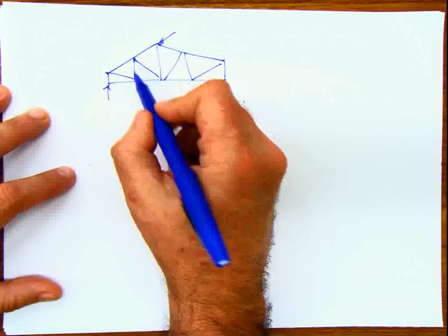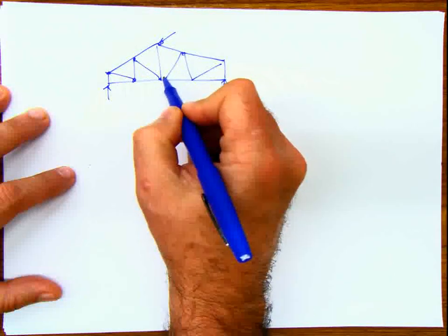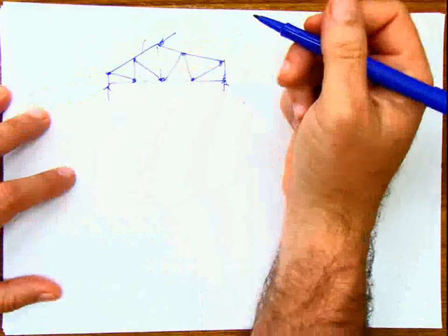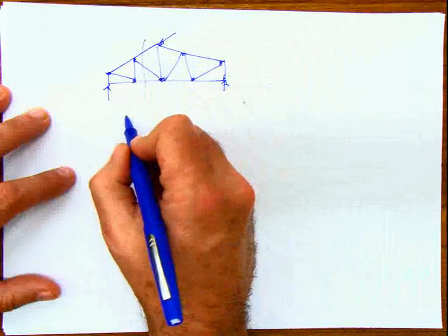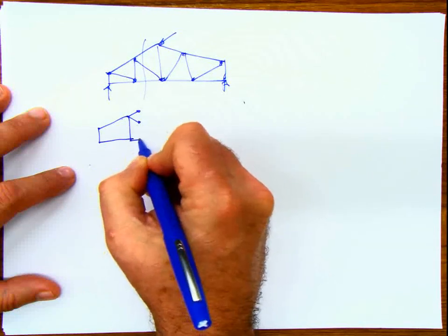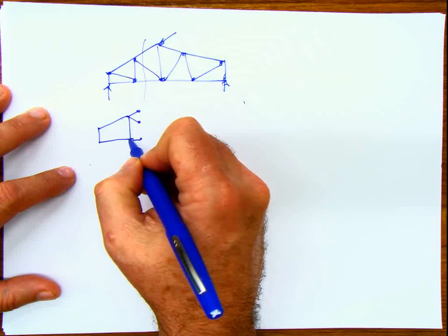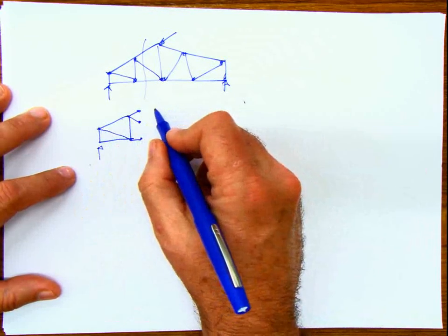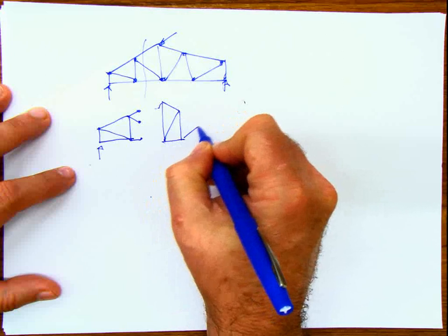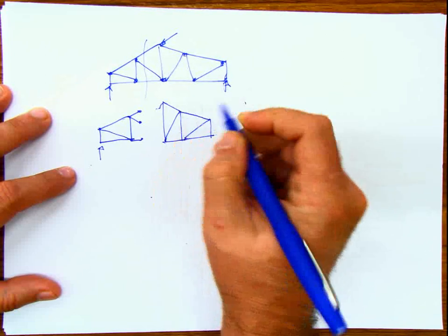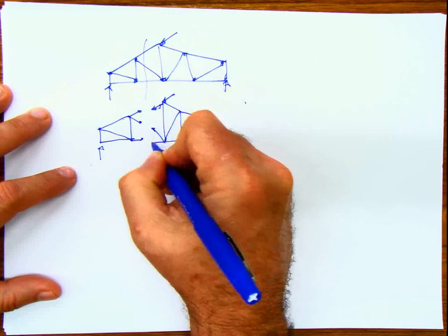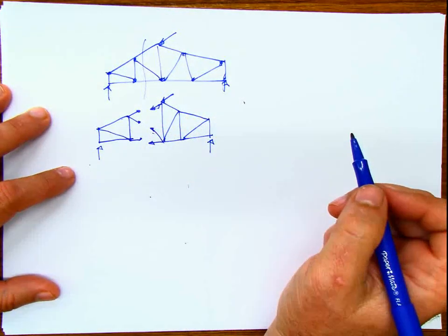We said that due to the nature of the truss, and how these are smooth beams and all the forces are applied only at the joints, if I make a section or analyze a joint or check any of the points, basically what we have is that in that truss, internally, all the elements are going to be subject to internal forces, and those internal forces are going to be only either tension or compression. Tension or compression, that's it, nothing else.